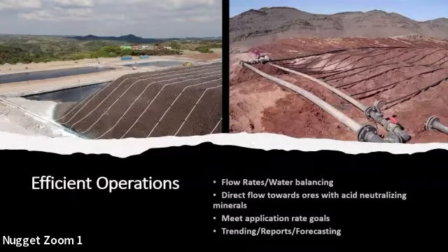There was also a correlation taken from the piezometers placed within the heap, taking into account all the samples that were taken to the lab for saturation tests or moisture content. For this material in particular, there are no higher concerns in terms of liquefaction, static or dynamic.